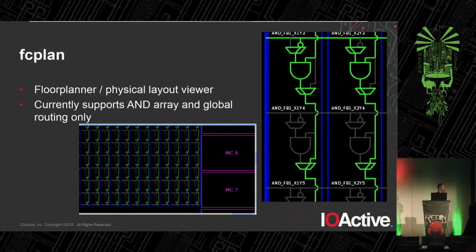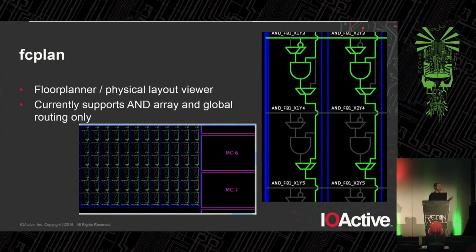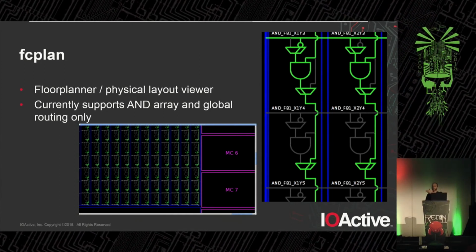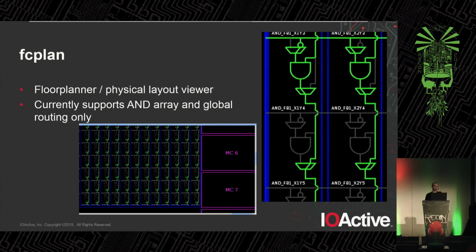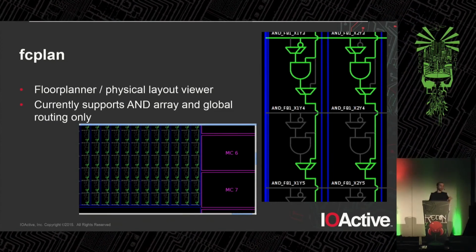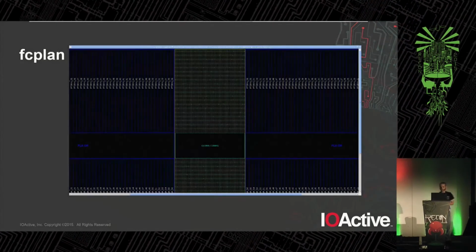The macrocells also, I've reversed some of the bits, not all of them, but I have not yet written code to actually render the appearance of them as checkboxes for, okay, this Schmitt trigger is enabled, the terminator is enabled, the slew is fast or slow, and so on. So those all remain on the wish list at this point. The configuration bits are known. You can access them from Libcrowbar. You cannot do so in the GUI.